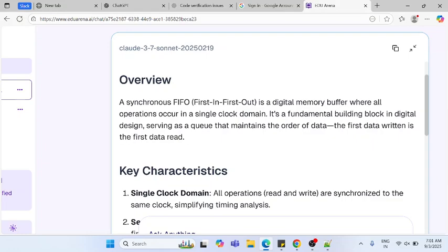Let us take write enable equal to 1 as writing and write enable equal to 0 as reading. When write enable is 1 and address and data are given, internally it will store the data. And when we want to read data from the memory, write enable can be moved to 0, so that when we give the address, the data in that particular address can be read back. This is the basic structure of your static RAM.